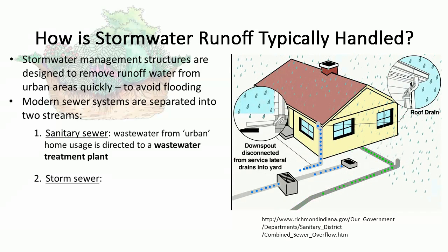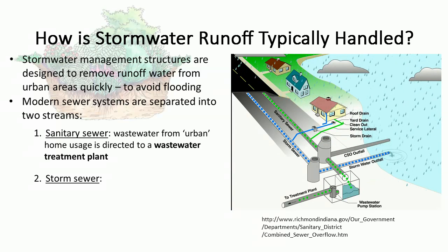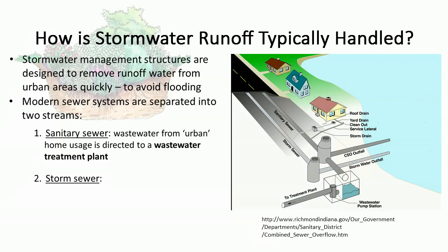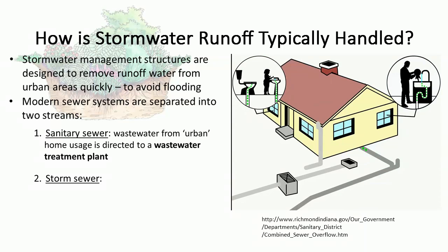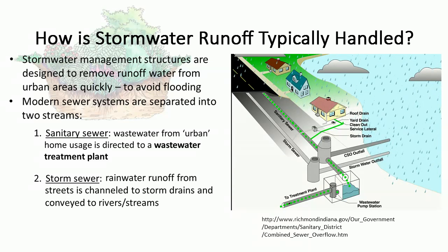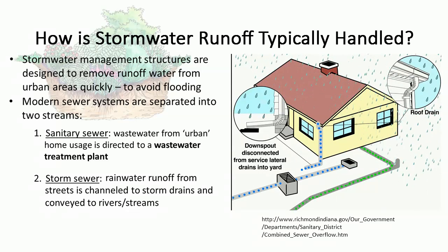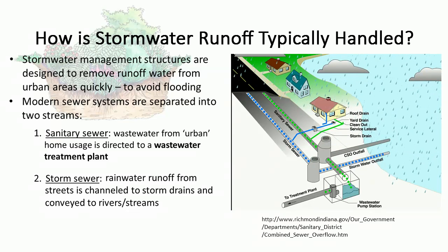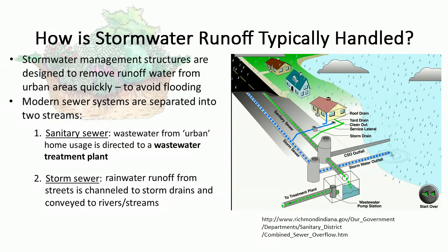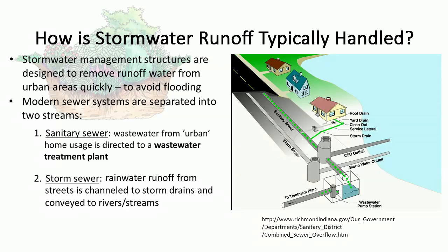Municipal sewage is diverted to a wastewater treatment plant in a sanitary sewer, where it is treated to remove solids, pathogens, excess nutrients, really anything that can devastate an aquatic ecosystem, back to acceptable levels before discharging the clean water into the nearest lake or stream. Unlike sewage, stormwater runoff is not treated before it is discharged. Runoff is conveyed to a separate storm sewer using storm drains located alongside roadways or in parking lots. The runoff travels through a series of underground piping before finally making its way back into rivers and streams at various discharge locations.